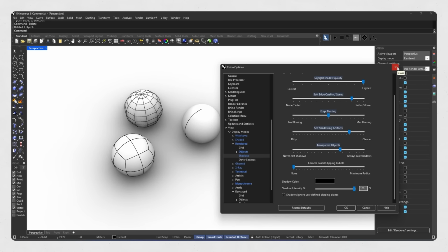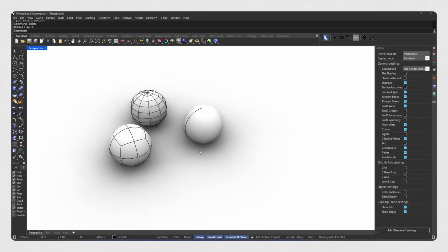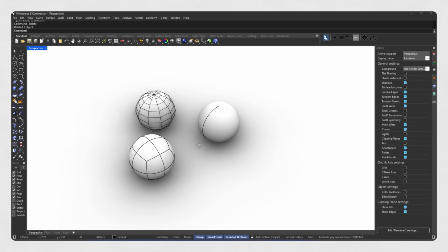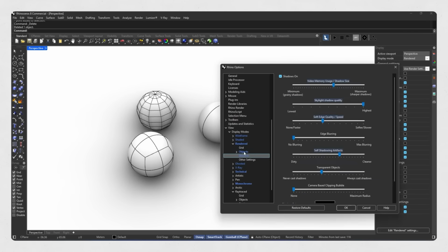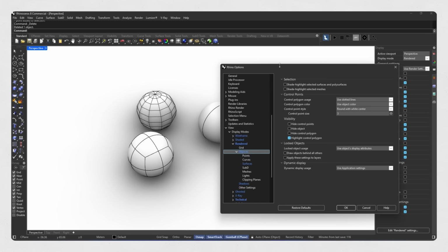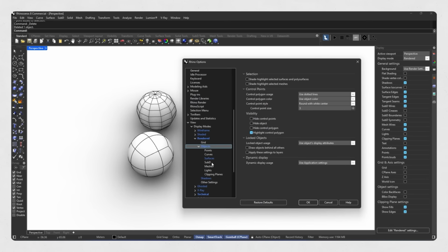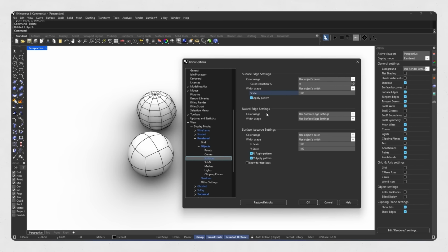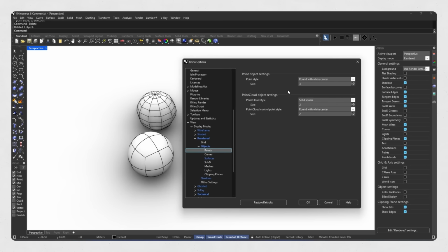In this very section of display options, you can customize the display of every type of element, seriously. We're talking about line width, colors, display scale, style, transparency, patterns, like dashed or continuous. For example, if you want those edge lines to pop out more in rendered mode, you can crank up the thickness. Or if you're dealing with a ton of points on your model, just shrink their size a bit and you'll get a much clearer view.